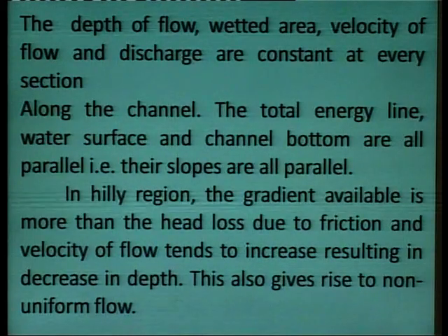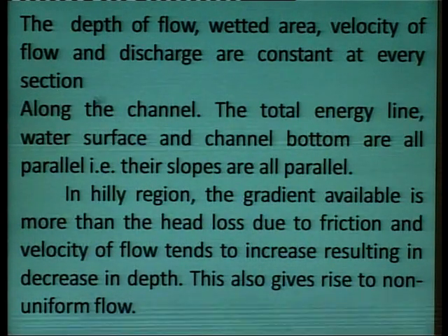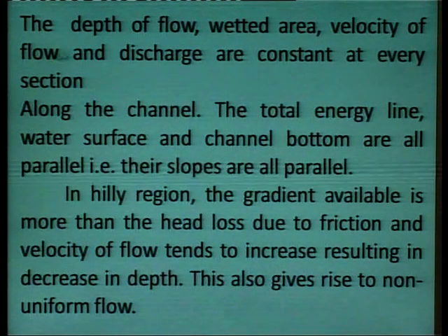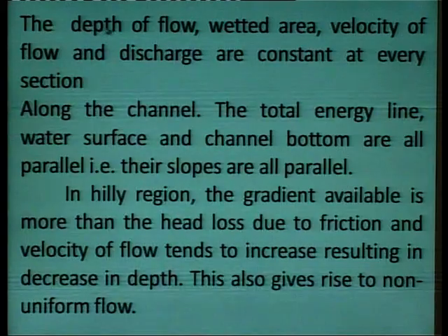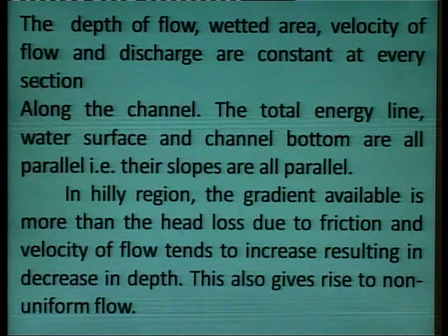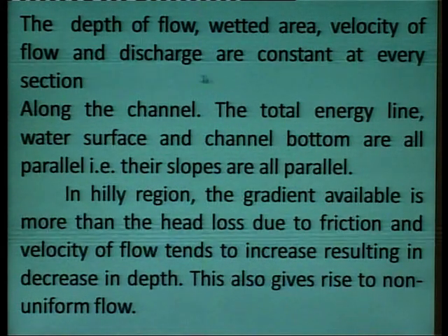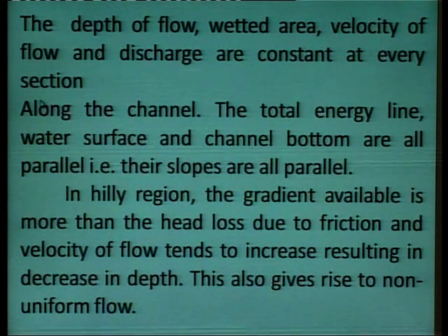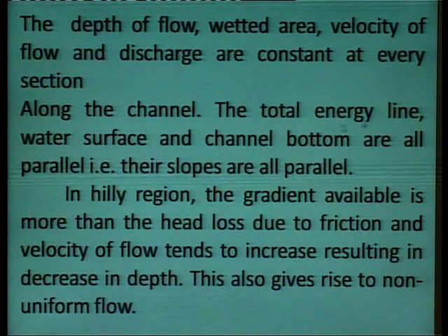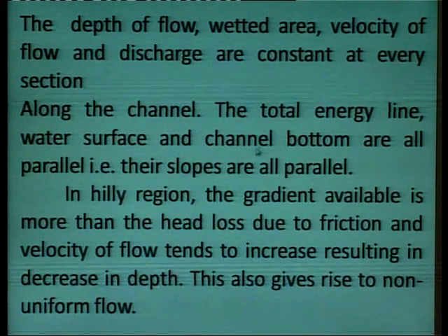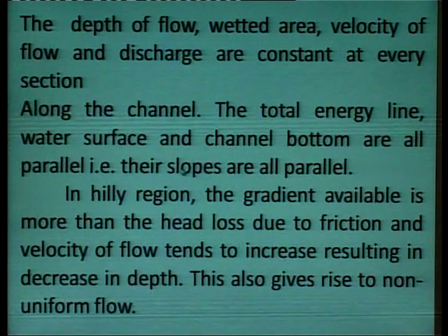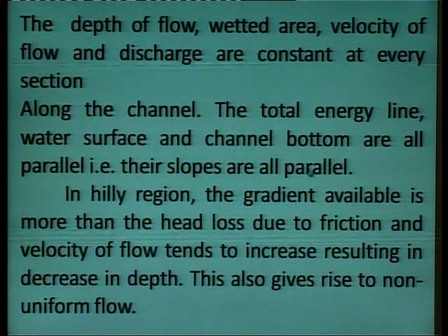The depth of flow, wetted area, velocity of flow, and discharge are constant at every section. Along the channel, the total energy line, water surface, and channel bottom are all parallel. That is, the slopes are all parallel.